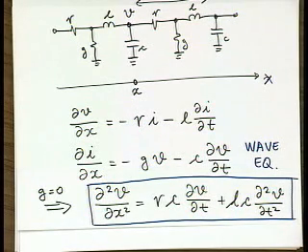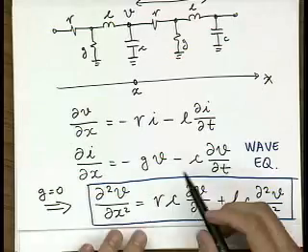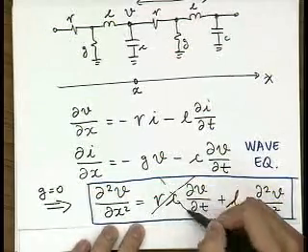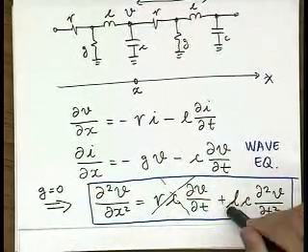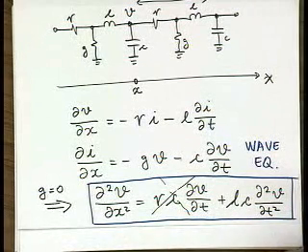And so now let's focus on the scenario where we are analyzing PCB level wires, where we assume that we have very wide wires that have a very low resistivity, that we use copper, and that we do all we can to reduce the impact of resistance. And then in that case, we can simply ignore this term and analyze what's really happening with this LC business over here. How does the signal propagate through?